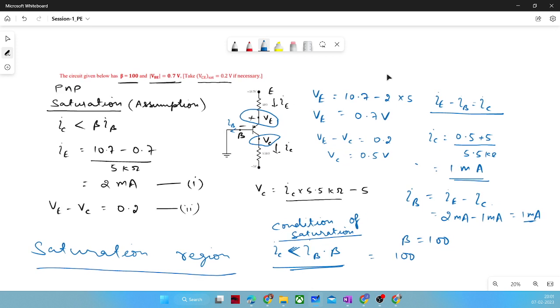One question regarding question 9 of the BJT assignment. That P loss is considered as P conduction plus P switching plus P off period loss. Yes, we have to take three losses, isn't it? Yeah, three losses, or you can say four losses, switching off and switching on losses, but if you consider it as a single switching loss, then three losses.